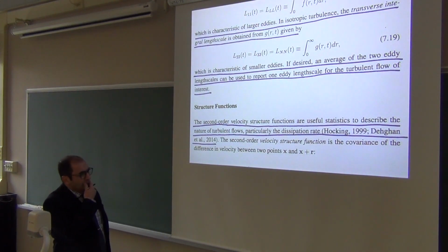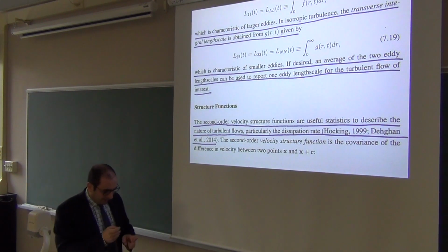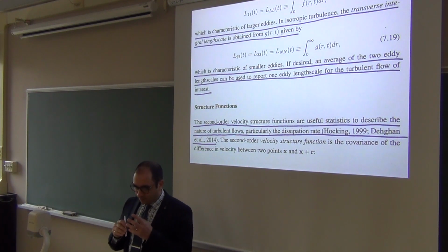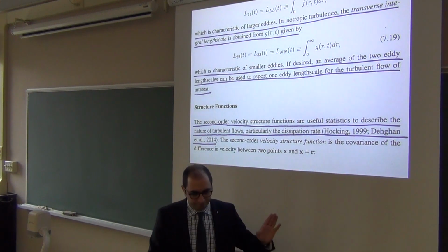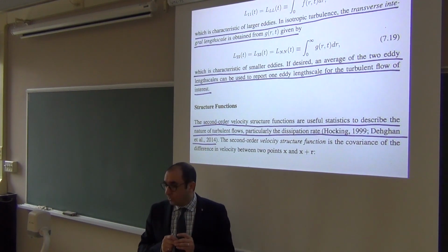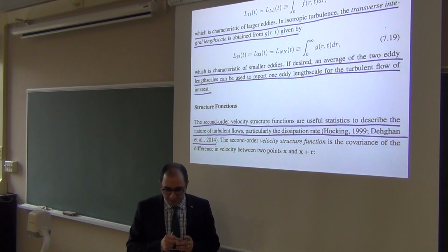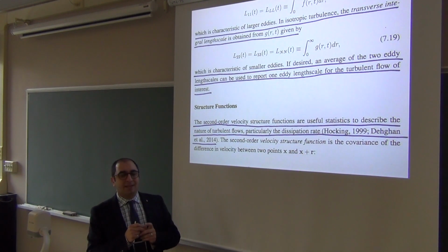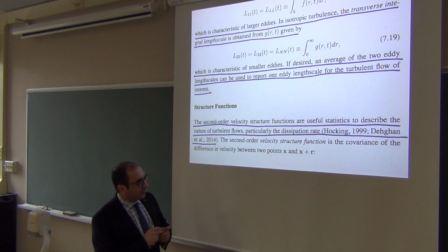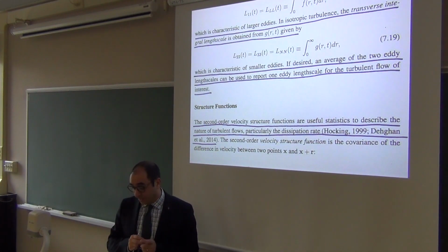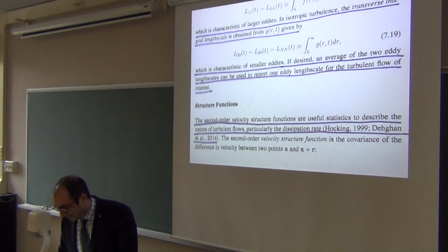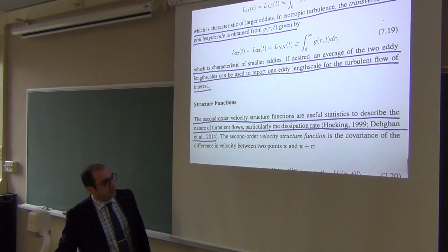And as we said, dissipation rate is a big deal. You must be able to quantify what dissipation rate is, and that's how you can solve engineering problems. And dissipation rate, if you remember, solely describes the nature of fluctuations in the inertial subrange, and along with kinematic viscosity, it describes the nature of fluctuations in the dissipation range. So it's a big deal. You must be able to characterize it. The structure functions will help you do that.